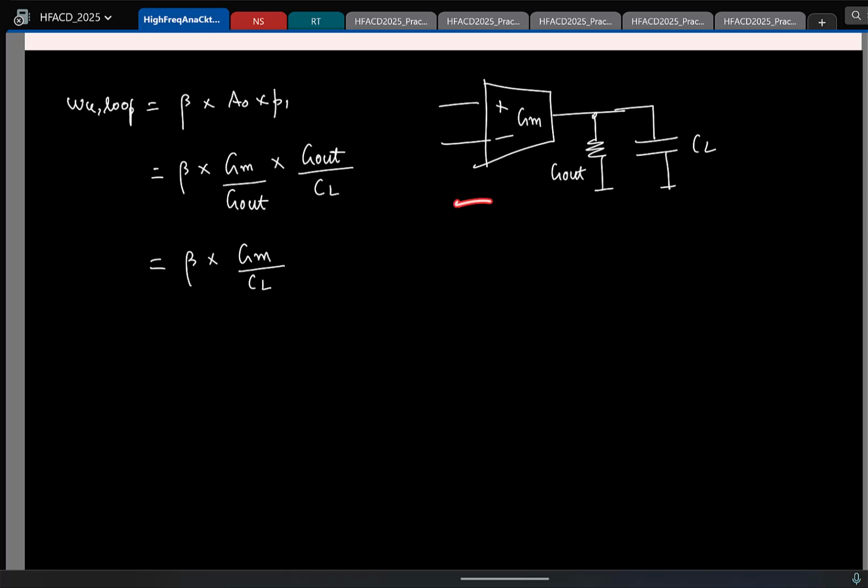So as you see, for a first order or single stage OTA like this, where you have the dominant pole at the output, the unity loop gain frequency, or for that matter the unity gain frequency, only depends on the short circuit transconductance GM and the load capacitor CL. Whatever we have been doing to increase the gain has been affecting only the output resistance. Changing the output resistance increases the DC gain but decreases the pole location. Those two effects cancel.